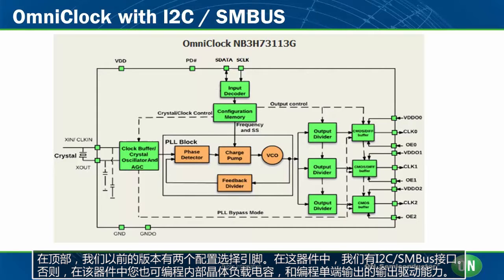On the top, in the previous versions, we used to have 2 configuration select pins. In this device, we have an I2C SMBus interface. Otherwise, in this device, we also allow you to program internal crystal load capacitors, and we also allow you to program output drive strengths for single-ended outputs.